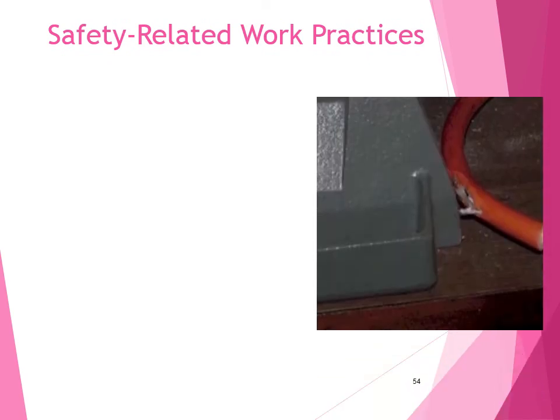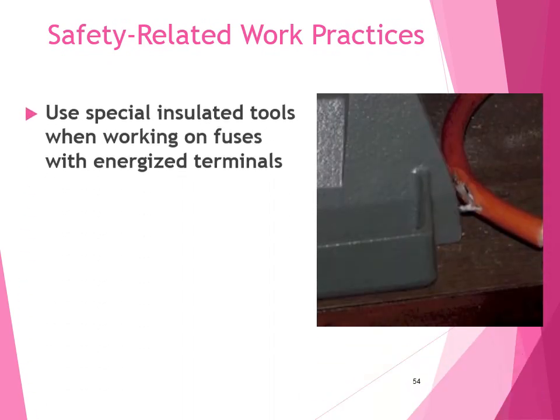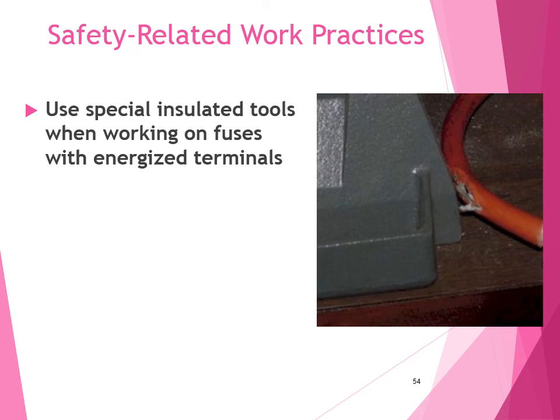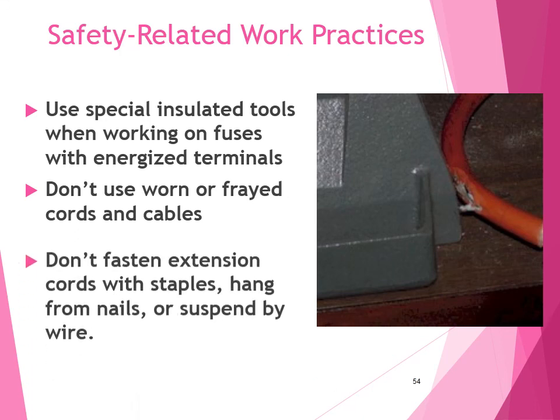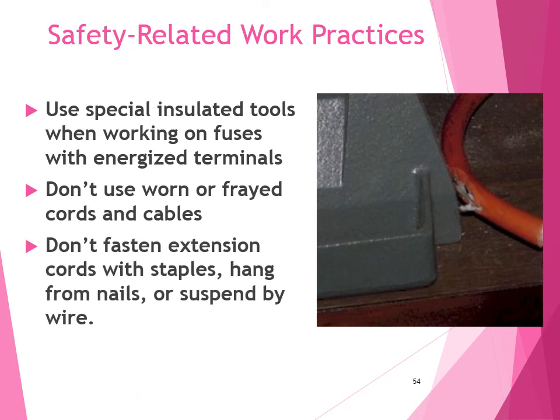Safety related work practices. Use special insulated tools when working on fuses. Don't use worn or frayed cords or cables. Don't fasten extension cords with staples, hang from nails, or suspend by a wire.